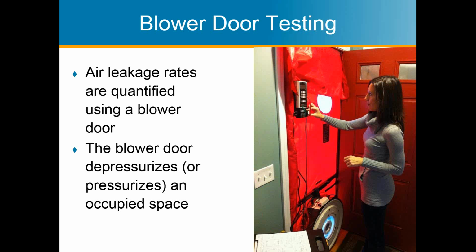The pressure of the blower door is not enough to affect animals and birds and people. It's totally safe to run with them in there. It's not safe at all to run if there's a fire in a fireplace, of course. That's the big thing you have to worry about. But what it's doing, like I said, is figuring out how much air you need to continually pump into the house to maintain the pressure. And what that's really telling you is how many holes you've got in the house.